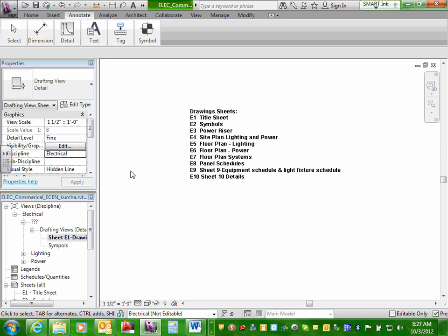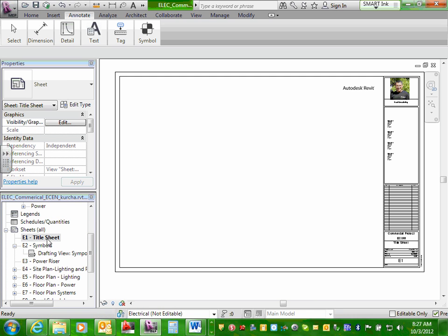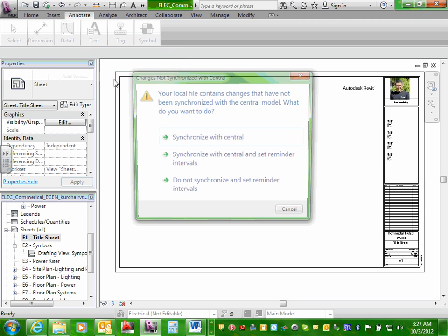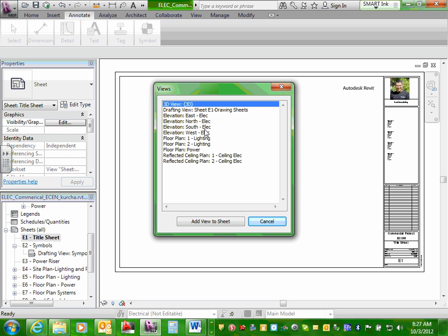Now let's go drop the E's. Where do you guys think we're going to drop the E's? Anybody have any idea? We're going to go drop the E's in sheet number 1. So when you guys are done, I'm going to go to E1. Can you guys follow up with me in that one? I'm going to go to E1, right click, add a view, synchronize with central because we're synchronizing. So synchronize. I'm going to add this drafting view into sheet number 1. Everybody see what I'm trying to do?